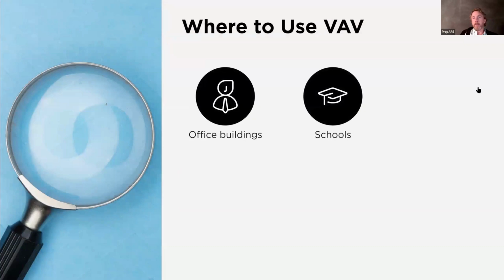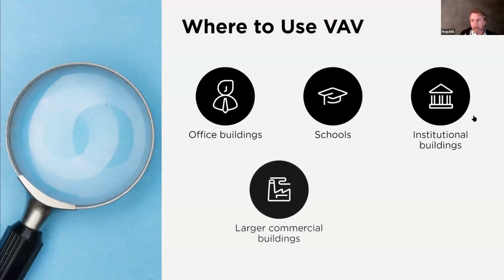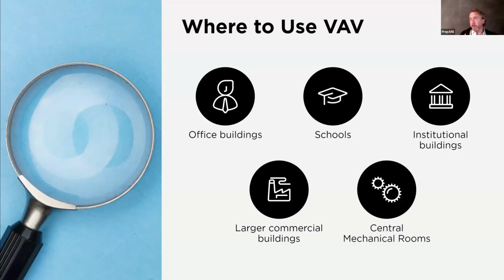Where to use VAV. Definitely remember this. So if you're preparing for PPD, take a snapshot of this. VAV is appropriate for office buildings, schools, institutional buildings, large commercial buildings, and it's going to have centralized mechanical rooms.